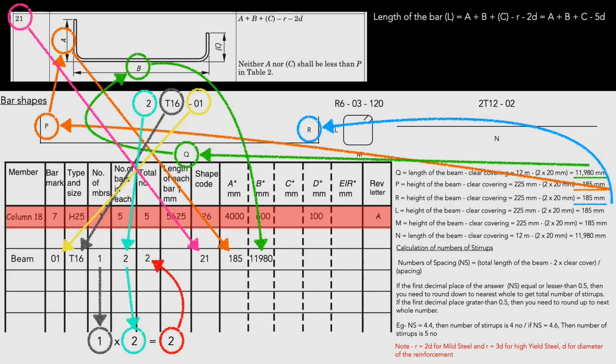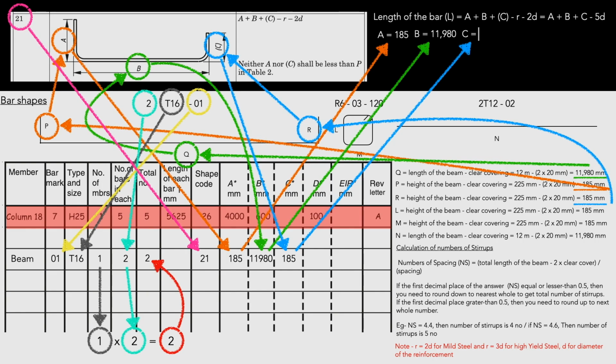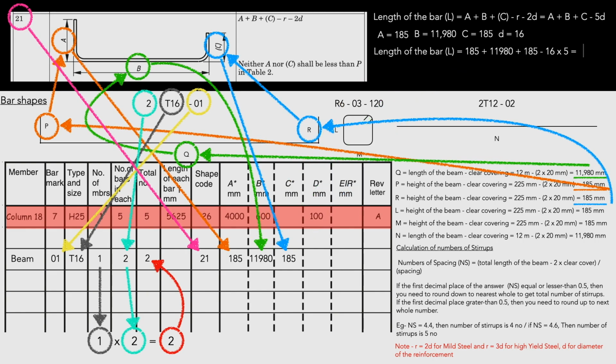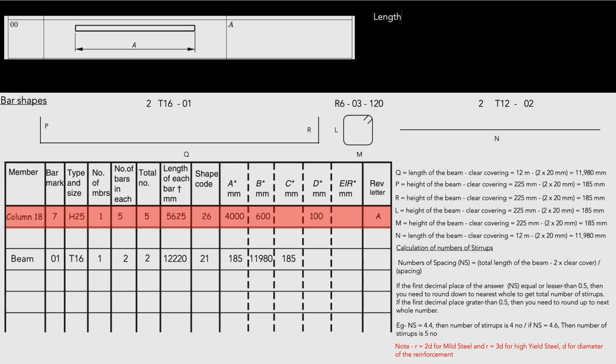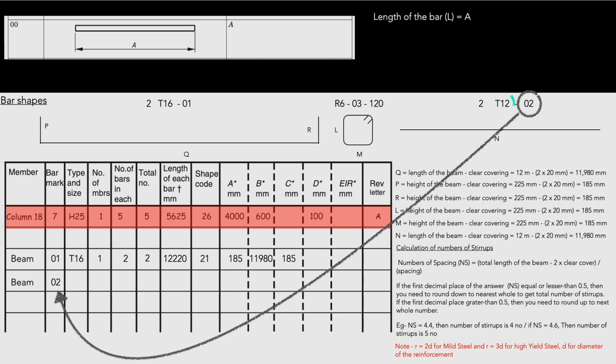The formula is the key to calculate the final length of the bar, as illustrated here for bar number 1. Bar number 2 is a 12 mm diameter high yield bar bearing shape code number 0. The way to calculate its total length is shown while illustrating different relationships.